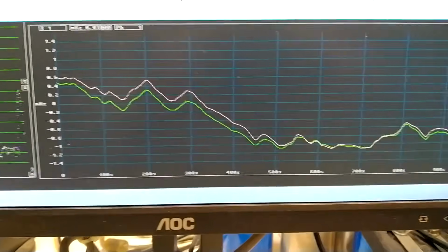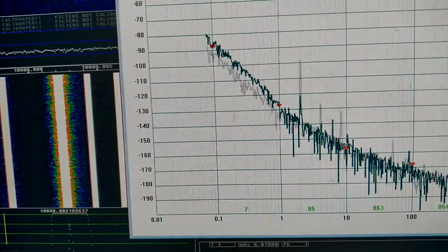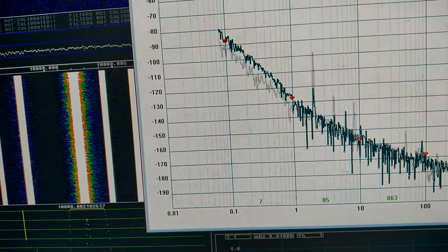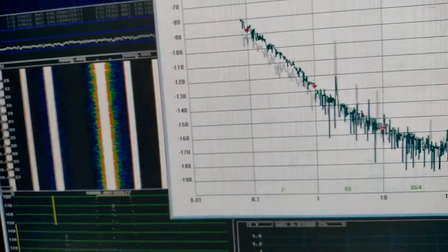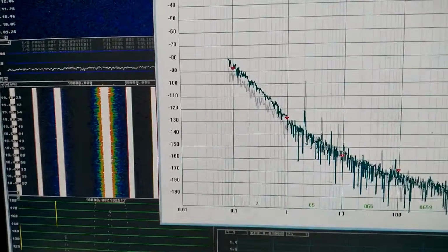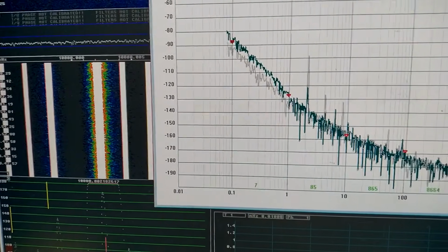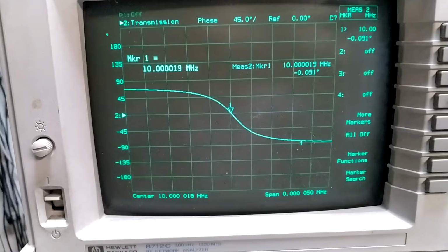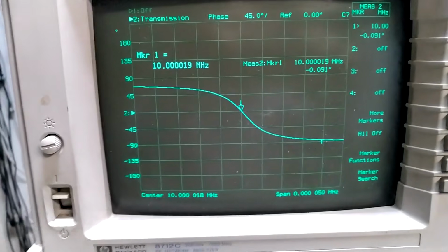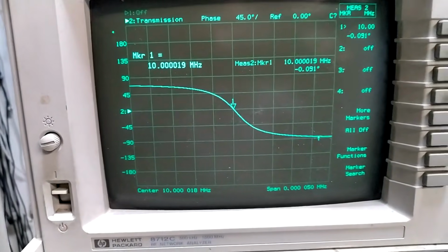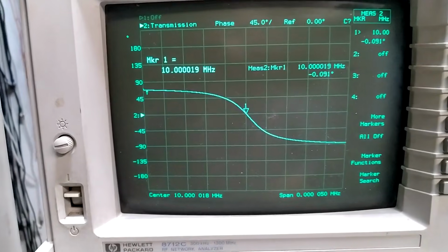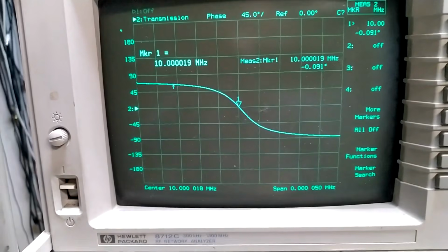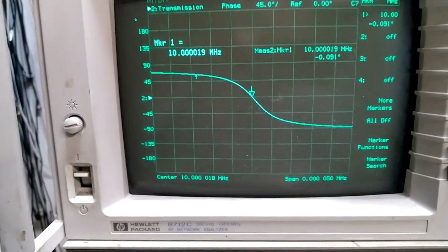The frequency instabilities have come back, and that is clearly seen in the phase noise at 0.1 Hz. It's degraded by about 10 decibels now. So it must be chaotic air movement inside the box. I think I have lost 2 decibels, from minus 133 to minus 131. This could be because I removed the stop band transformer.